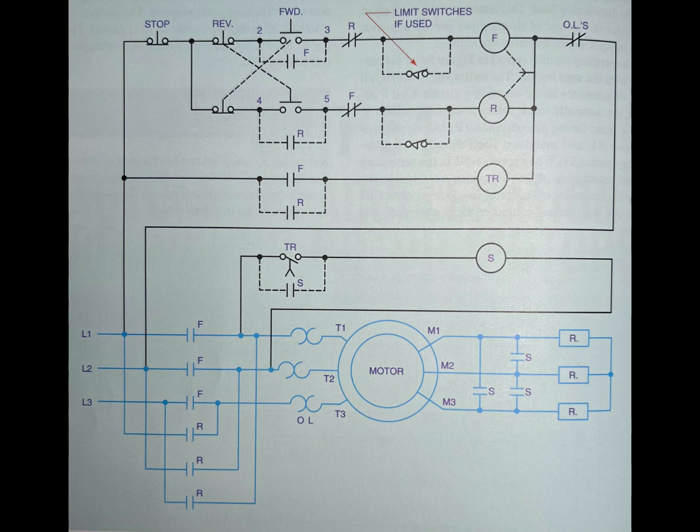As the rotor accelerates, the magnetic fields induced in it almost match the rotating magnetic field of the stator. As a result, the number of lines of force cut by the rotor is decreased, causing a decrease in the frequency and voltage of the rotor. The rotor never becomes fully synchronized with the rotating field.